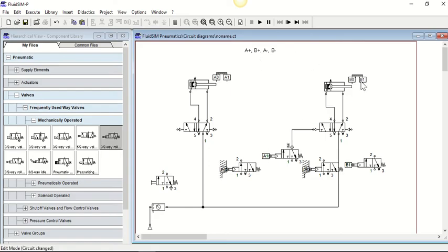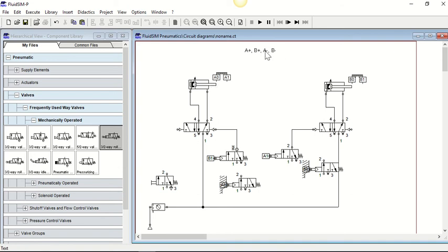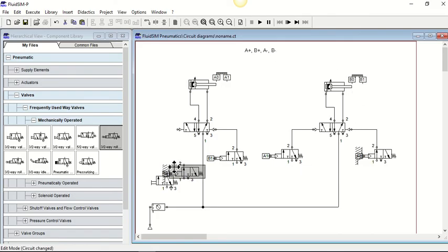Then when B goes out, it hits B1, and that's going to be the input to send A back. Then when A comes back, it hits A0, and that should be the input to send B back. And finally when B comes back, it will hit B0, and that will help you start your sequence again. That loops it back around so that your sequence is repeatable.